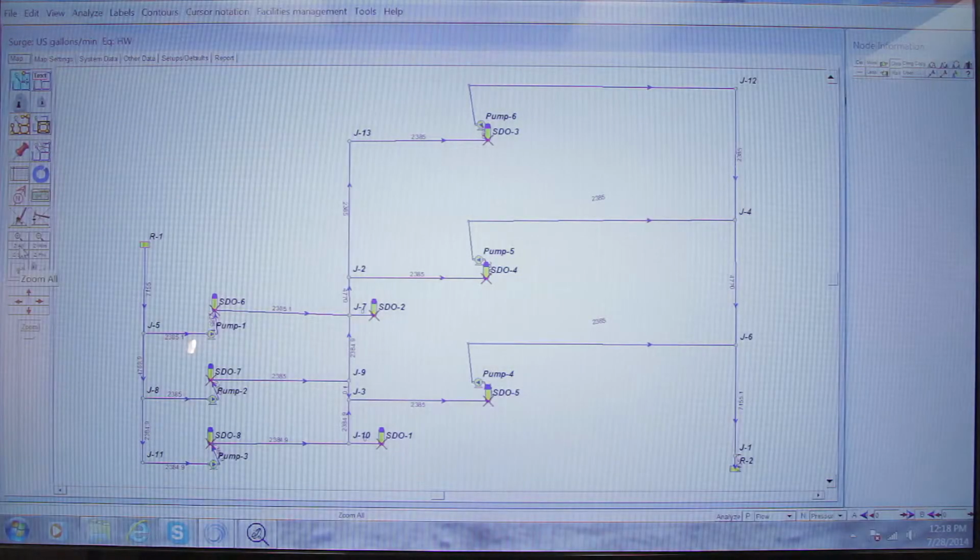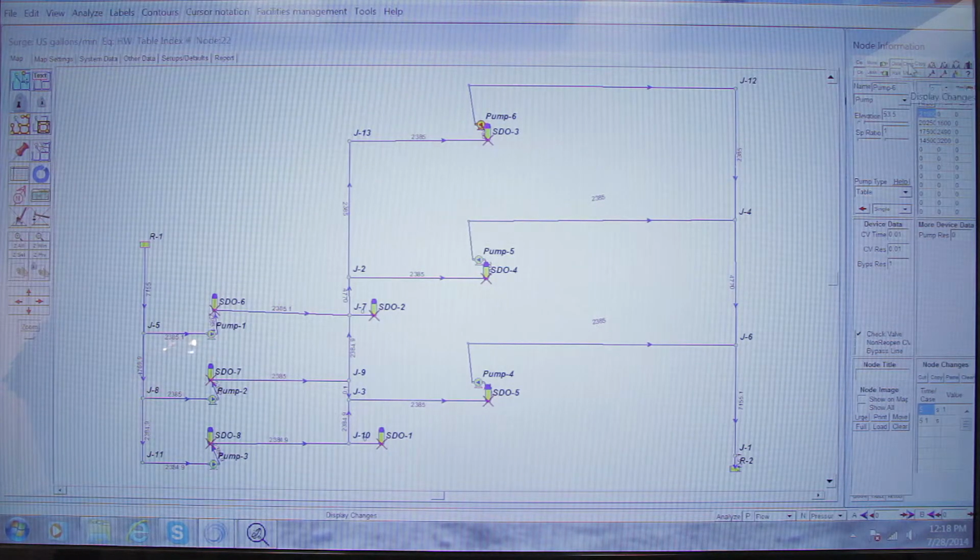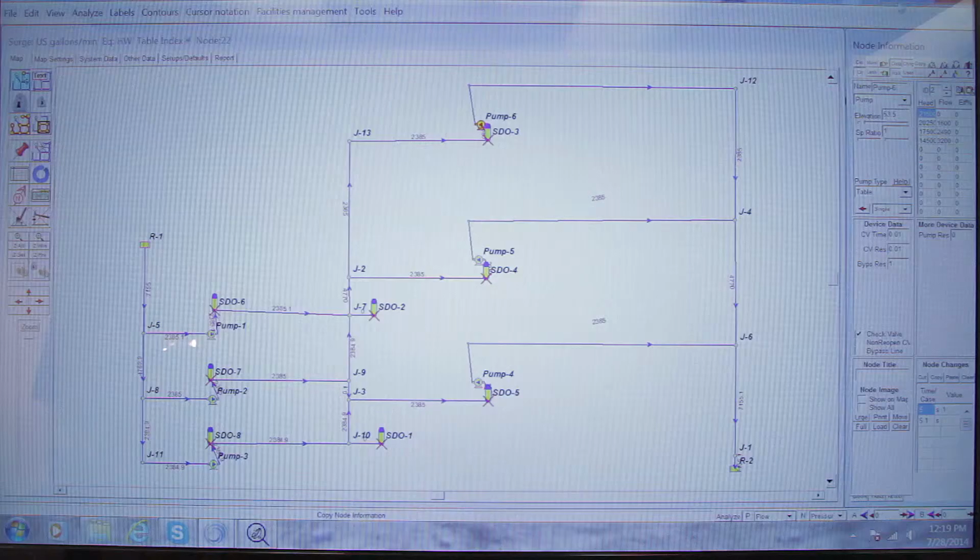So we've run the model and we're basically looking at the injection pump, which I'll grab on the model, and we're looking at data as we're fracking a well. In this pump, we have a pump trip. What actually happens in Mother Earth, okay? So if we look at our steady state pressure, we'll grab a node on the top side here